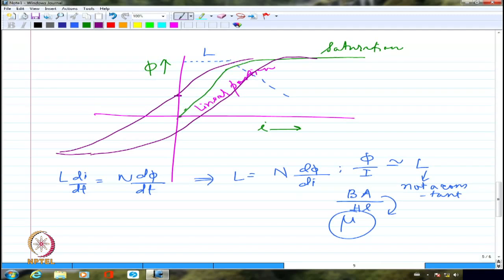Right? So this particular hysteresis property is a pain in the neck in many of the alternating current machines, because it will first of all eliminate the linearity. If I simply try to assume that flux and current are linear even in the beginning, that is not going to work. So the linearity property is lost, which will give rise to several non-linear behavior,